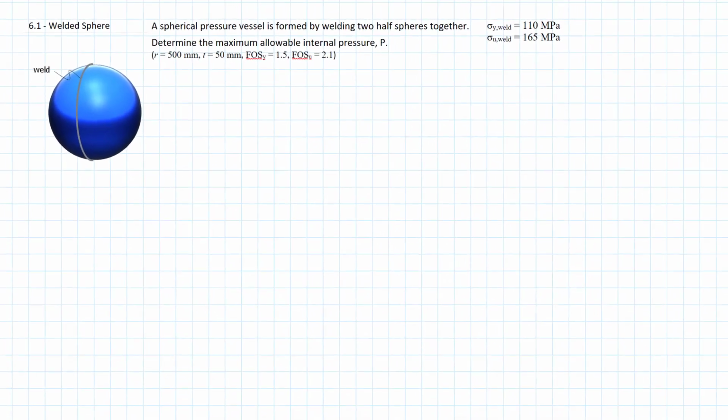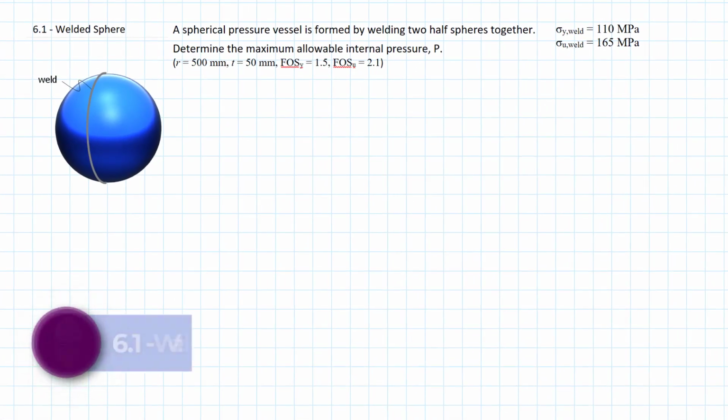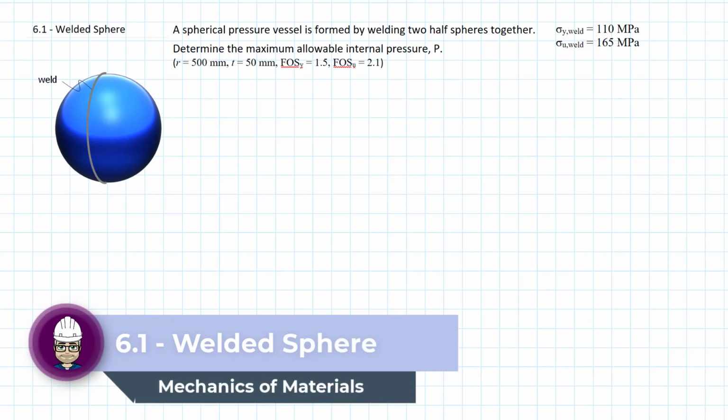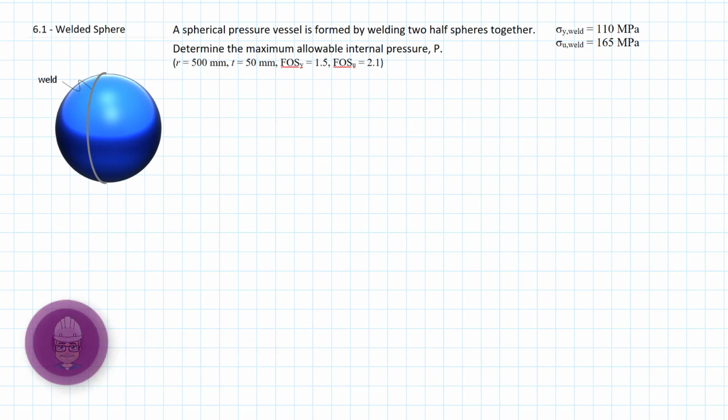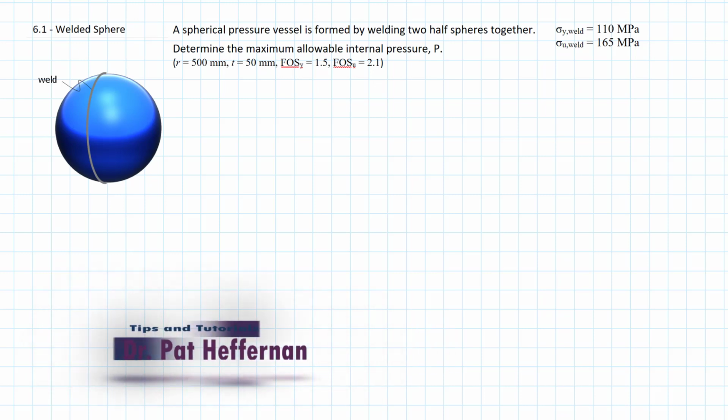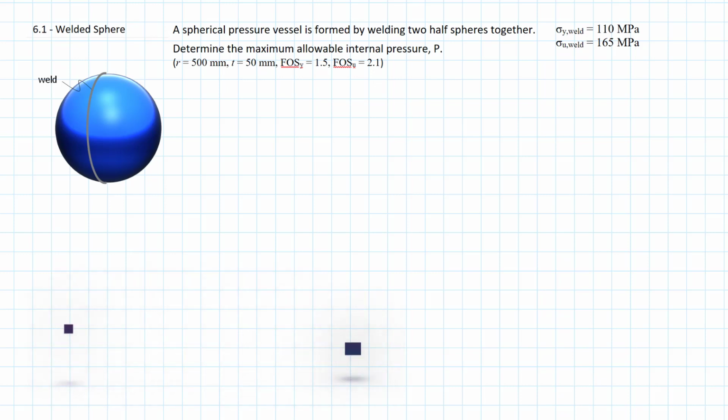So we've started to talk about combined stresses or combined loads, where we take a number of different methods of loading and we start to put them together. And of course, we're using superposition because we're still in that linear elastic range. And so the net result on our differential element, as far as stress goes, is the net sum of things. And so one of the first places that we looked at, because it offers stresses in multiple different directions at the same time, was pressure vessels.